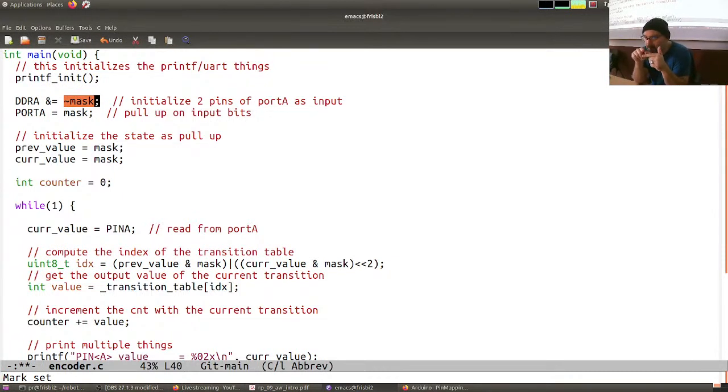And then in order to clear only the 2 bits that are in position 0, you do a bit by bit AND operation between the value which was already contained in the port A and the value of the negated mask. And this basically clears the last 2 bits, but leaves all other bits unattended, because if 1 bit, which was not of the last 2, was at 0, the result of the AND between 1 and 0 is 0, so it stays the same. If the bit was 1, then the result of the AND between 1 and 1 is 1. So basically this preserves the status of the existing digits in the port, right?